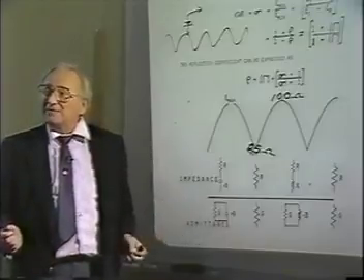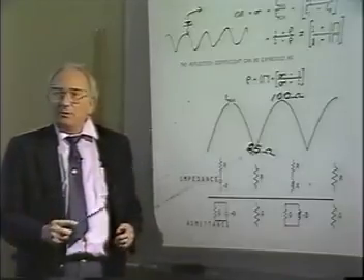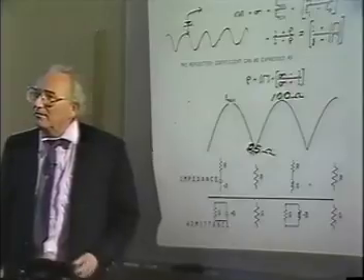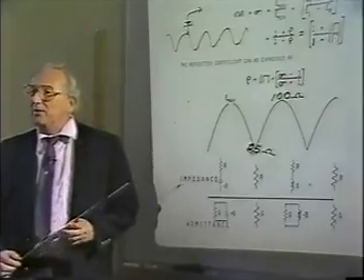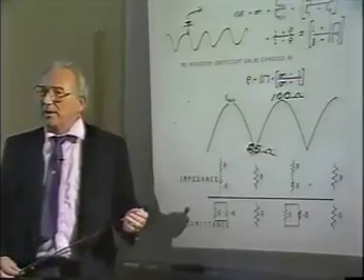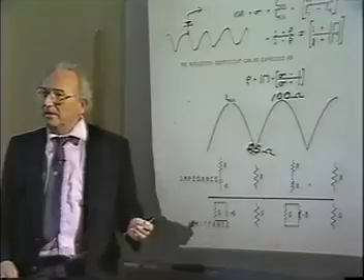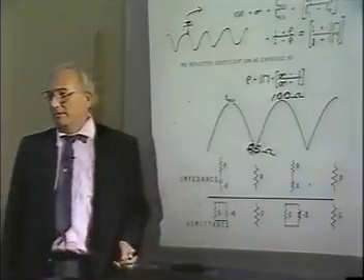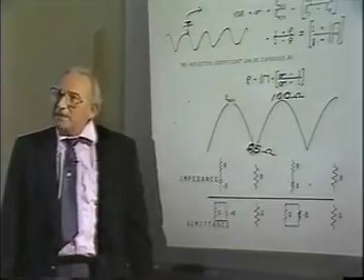Someplace then on this transmission line, if you have a standing wave pattern, you know that somewhere in between there, between Z max and Z min, is going to be Z0, right? We've already seen that. So a little later, I'll put another circle on one of these diagrams, and you'll see exactly where that 50 ohms will always be. It'll be located someplace between here and here. Not always at the same angle, obviously, but it's going to be located someplace back there, isn't it?